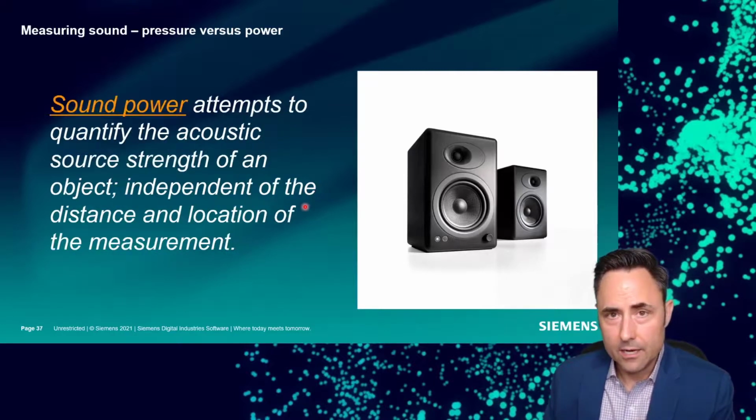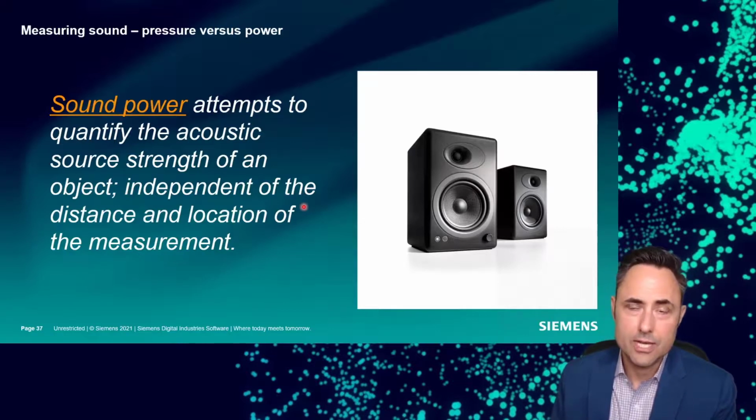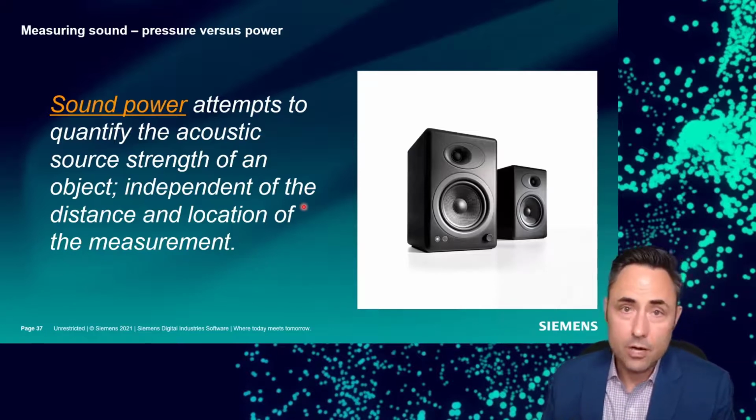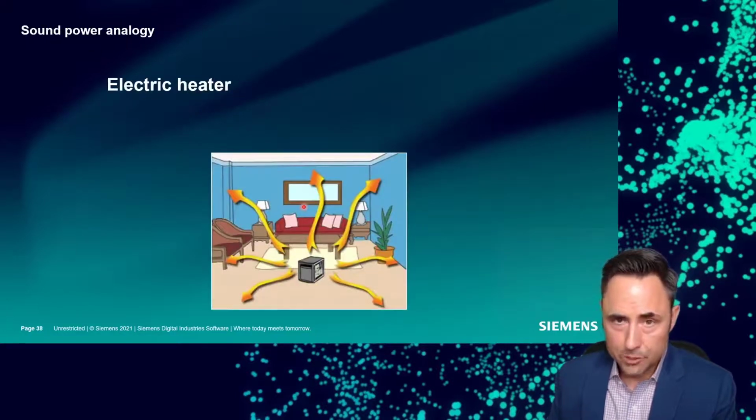The idea of sound power is that it alleviates all of those restrictions, and that we're trying to quantify something that is the inherent sound making ability of the object, its power, sound power, that we can measure and report independent of our distance and orientation of our mics and all that stuff. It's sort of an inherent number, okay? And that's why it's valuable.